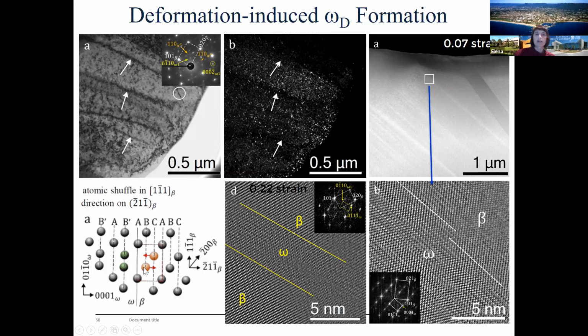We could have partial collapse or full collapse in the structure. So ω prime here, as you could see, these two atoms show partial collapse, and here we have full collapse. So this is the fully developed unit cell structure for the omega phase.